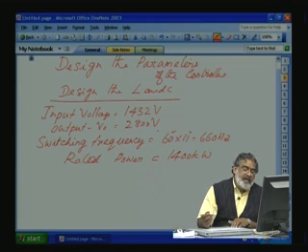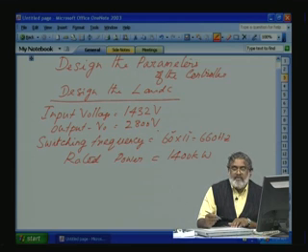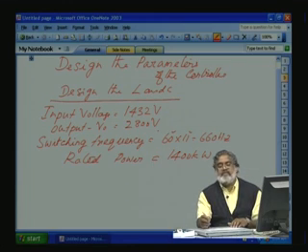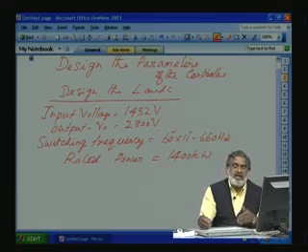So we already derived the equation. From the equation we can find out L and C, and once L and C are found out, using the standard technique used for the modulus, again we can find out the control parameters for the PI controller. Already we know that the control parameter for the current is a simple gain based on the L, the converter gain G and the triangle frequency. So this we will take up in the next class.